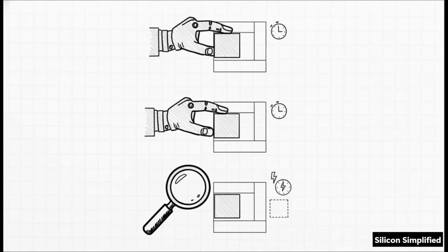And a peek? Well, it's kind of like a get, but it just copies the data without actually removing it from the producer. Successive peeks will return the exact same object. Oh, and remember, in SystemVerilog, blocking methods are implemented as tasks because they actually consume simulation time, while non-blocking methods are implemented as functions because they execute instantly.